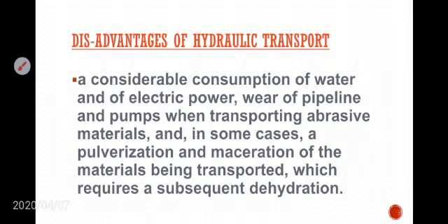And next, coming to disadvantages of the hydraulic transportation system. In disadvantages, we obviously discuss a considerable consumption of water. That means we need plenty of water. That is one of the disadvantages, and we also need more electric power in order to run the high pressurized bore pumps or suction pumps, and there is wear of pipeline and pumps when transporting abrasive materials.